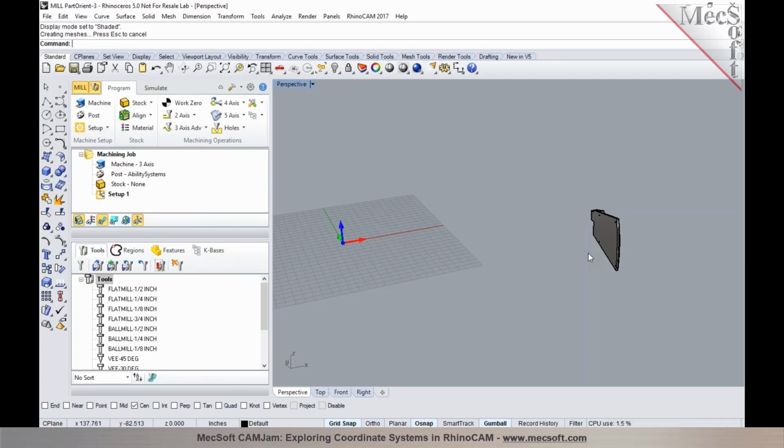So typically when the part is designed, you wouldn't be designing way out in space. You would probably be designing somewhere closer to the origin by picking one of the planes, the C planes or the construction planes. Since this may have been part of an assembly and exported out from an assembly as a part, you could have applied some mate relations to basically establish your assembly. So the part could have been out somewhere in space when it was exported from an assembly.